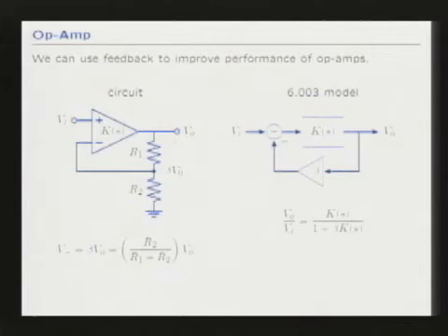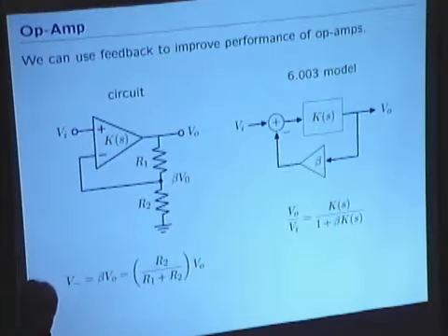right? We're going to take a circuit diagram and turn it into an integrator, gain, adder diagram, a block diagram. We're going to take a circuit and turn it into a block diagram. So the way we think about the plus and minus input of the op-amp is as a subtractor.